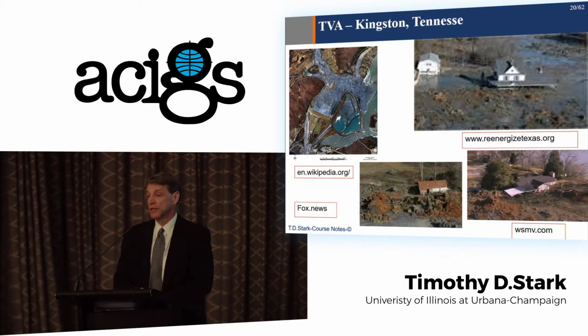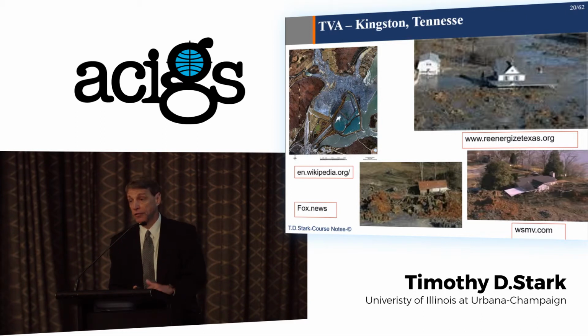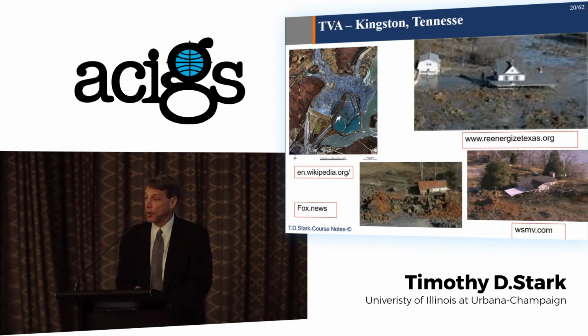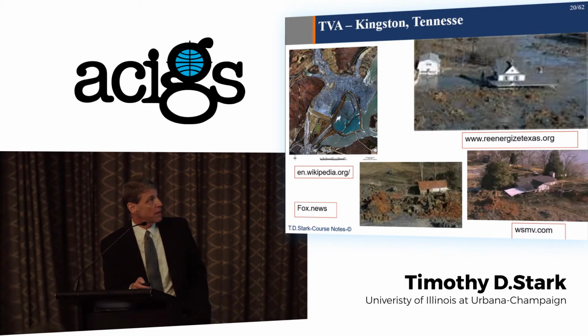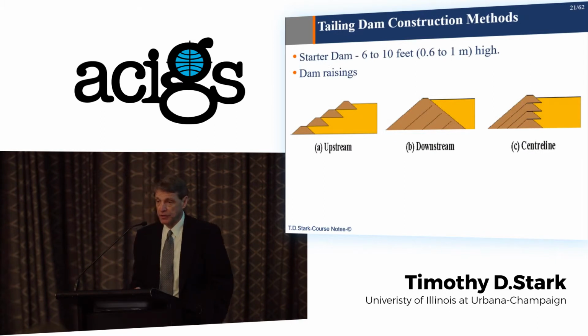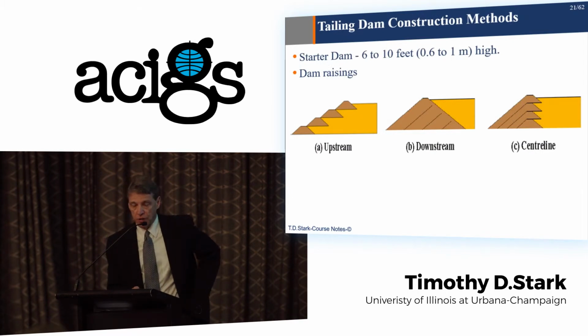This prompted the U.S. EPA to evaluate tailings dams and tailings ponds. So coal combustion residuals now, say fly ash, bottom ash, etc., FGD, all now must be placed on a single composite liner system in the United States. So in other words, all that material is being treated as municipal solid waste. So it has to be on a single composite geomembrane liner system.